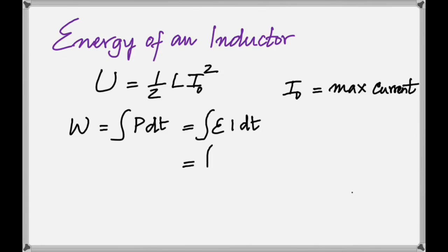Power is the product of voltage and current. And then I've substituted power is E times I, and then E is L di by dt, if you remember. And then the dt's get cancelled, and integral L i di. Yeah. Integral i di is, that's how you get it.